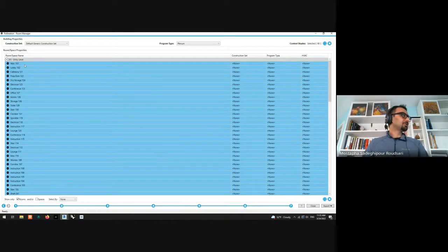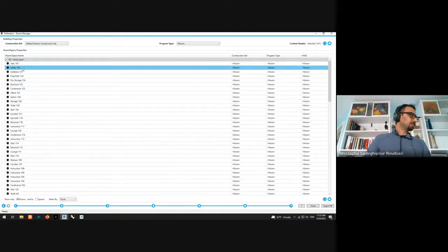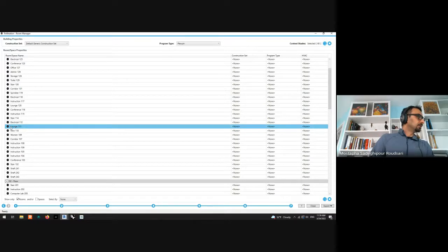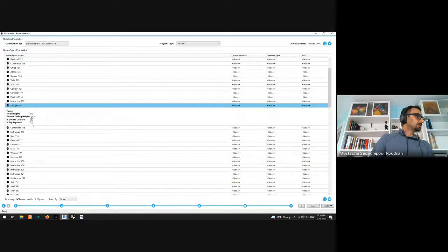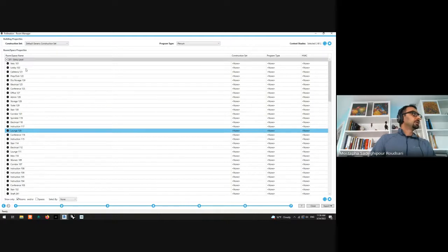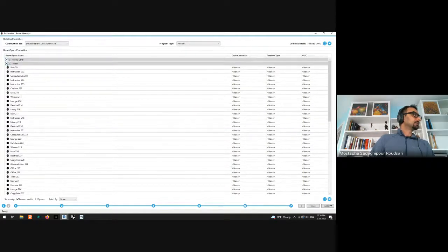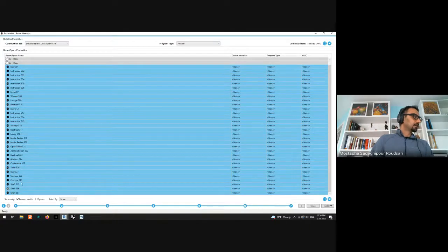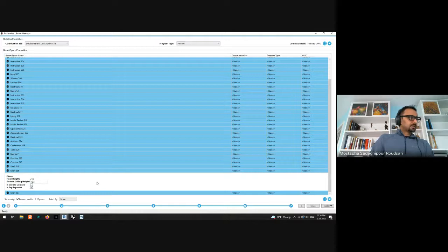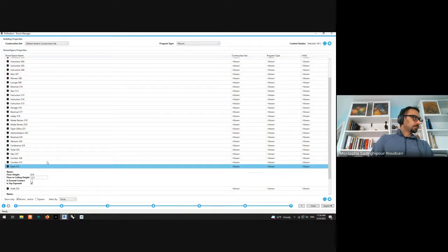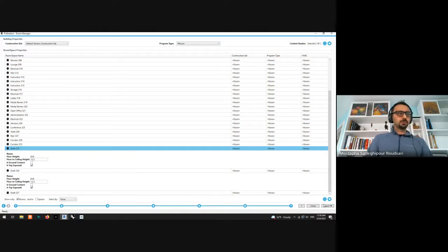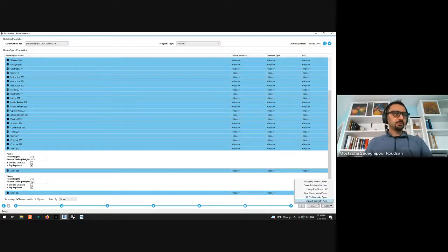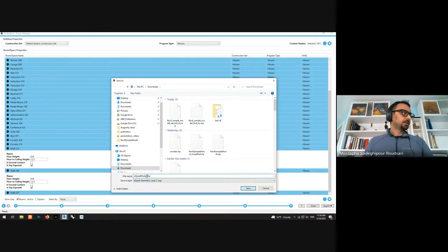If you had time, I wanted to show you there are things that you have to set up before exporting to eQuest. But because I already know about it, I can set it up. So this is not set up correctly. Maybe we do another presentation for that, but let me go to the 3rd floor and make sure everything has top exposed. So now I have top exposed. So I'm going to export, select everything. Export everything to eQuest. I call it eQuest model